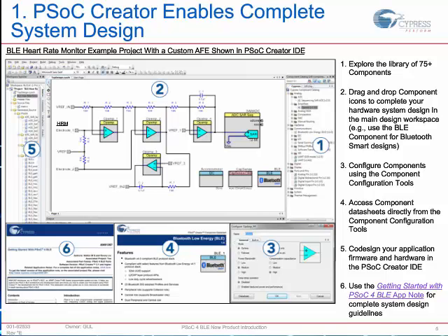Instead of working with a microcontroller that has fixed function peripherals around it, assigned to certain registers in a memory map and locked down to certain pins, PSoC is more of a programmable fabric that gives you, the engineer, the power to design the chip the way you need to. And you do this by dragging and dropping pre-built components, which are essentially hardware IP blocks that Cypress creates for you and offers through the tool PSoC Creator. You drag and drop these components onto your schematic, as you can see on the slide here, and wire them up to create a system. So at this point, what you're doing is you're defining at a chip level what your system will do from a schematic view. It helps you design the way you think. It helps you design, what you see is what you get sort of a system. But it doesn't stop there.